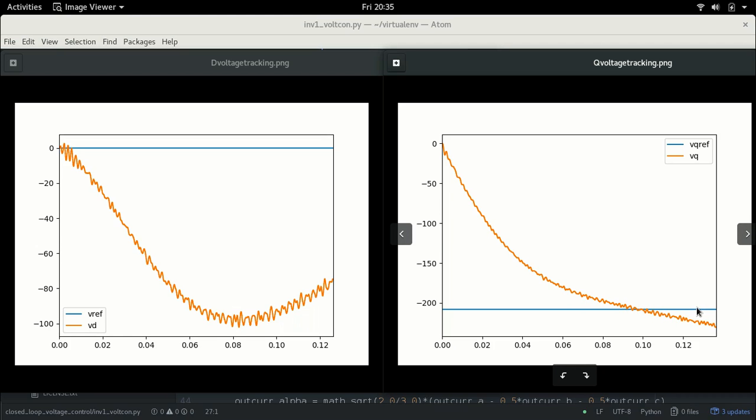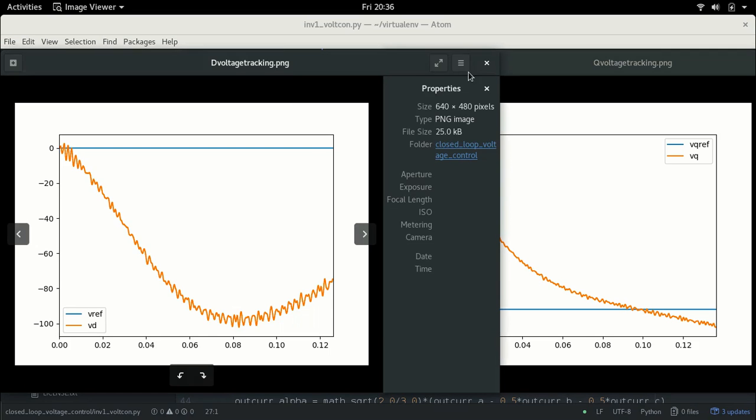But most importantly, you'll see here the reason is, in almost all power electronic circuits with an inductance, the D and Q domains are linked with each other. So it is not possible to change D independently from Q or Q independently from D. And so when Q is changing, D also has to change. These two are coupled. Any change in one does have an impact on the other. But with control, these two will eventually get regulated, and that's what we'll show. So let's plot it again.